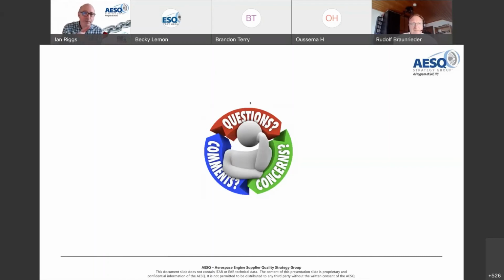I guess the only thing to add to that is, because the scoring is relative, if you did use the low volume throughout an FMEA, it's still going to give you a relative scoring on your RPN numbers. So as long as you're consistent with it, it shouldn't really change the risk profile that you will end up with. I would always steer away from using the low volume criteria, but there may be some genuine cases where it actually makes more sense. But if you're going to do it, be consistent throughout the FMEA when you use that scoring guideline.